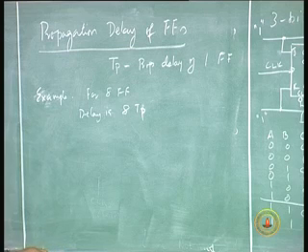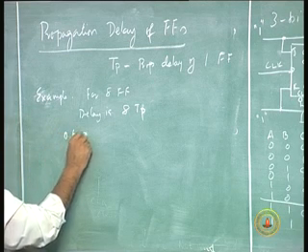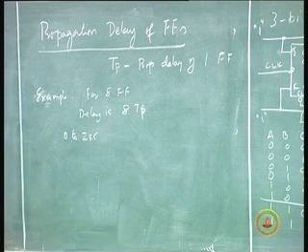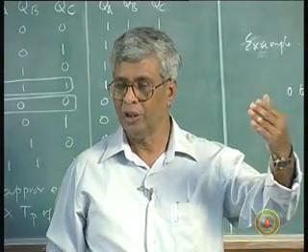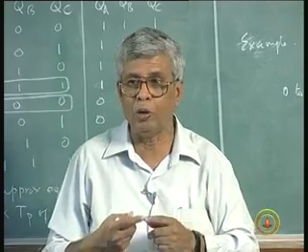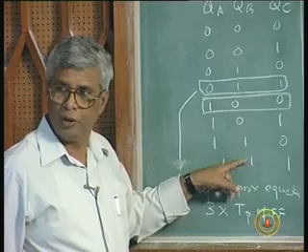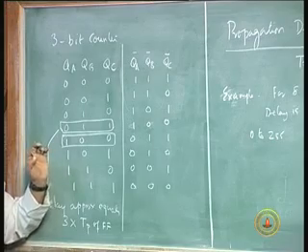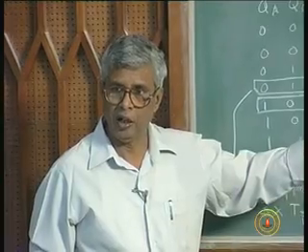So what is the count I can reach, from 0 to 2 power n minus 1? n is 8, 2 power 8 is 256. So for a count from 0 to 255, each count takes 8 Tp to materialize. If I am at 0, after 8 Tp 1 comes, after 8 Tp 2 comes, and so forth. Of course, something can happen faster than that; for example, from here to here there is no change in this flip flop, so it is going to come immediately, there is no question of propagation delay. It is not that each count is going to change only then. So I should allow for a maximum propagation delay of 8 times Tp in order for a count to be reliable.